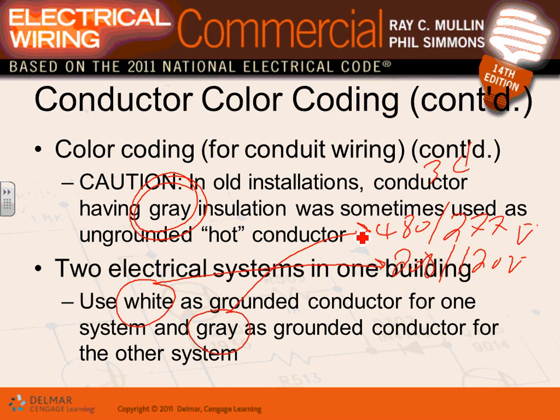Every panel has to have a label that says, by the way, 208/120 color code is black, red, blue, and white. And then on the panels right next to it, a 480/277 system, guys, is running as orange. What did we say? We have an orange, yellow, and brown. Brown, orange, yellow, and gray. See, these are the colors that you have to identify them.